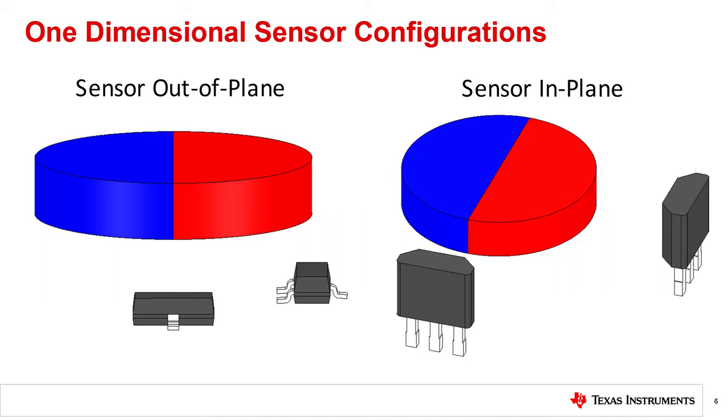This configuration does have a few drawbacks, which include that the application may have limited physical space available for the exact placement of two sensors. There may be sensor alignment errors that occur during assembly, and sensitivity errors that result from device-to-device variations must be accounted for.